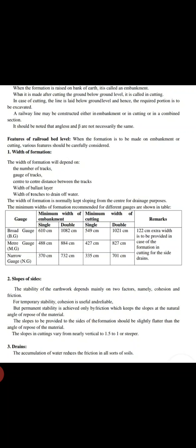The slopes in cutting vary from nearly vertical to 1.5 to 1 for stiffer soils. The accumulation of water reduces the friction in all sorts of soil.